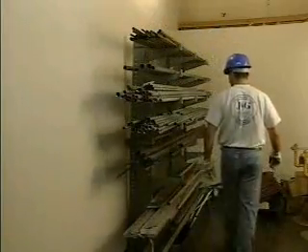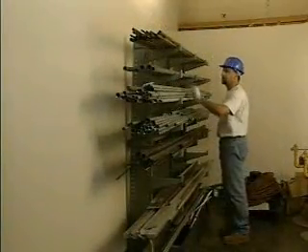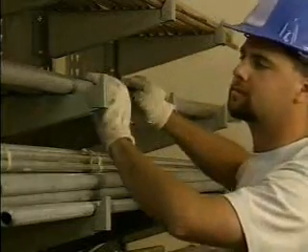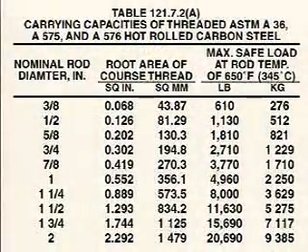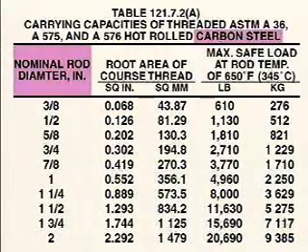Though pressure is generally the concern of piping system designers, it is important for maintenance personnel to understand schedule numbers in order to identify the proper pipe for a specific job. The American National Standards Institute, an organization that publishes guidelines about pipe materials, sizes, and applications commonly used at many industrial facilities, has developed working pressure ratings for different types and sizes of pipe. The working pressure rating lets piping system designers, as well as maintenance personnel, know the amount of pressure a specific size and type of pipe can support.